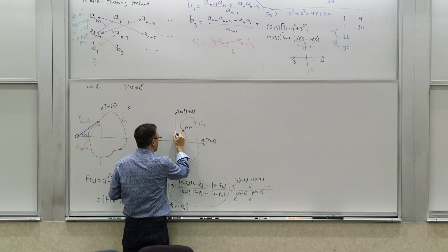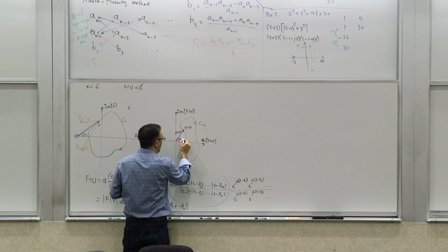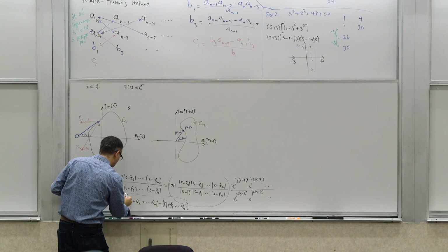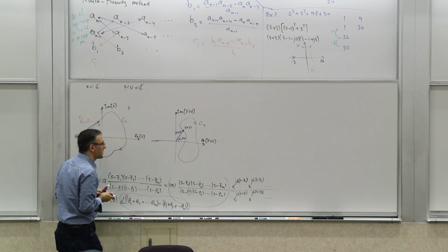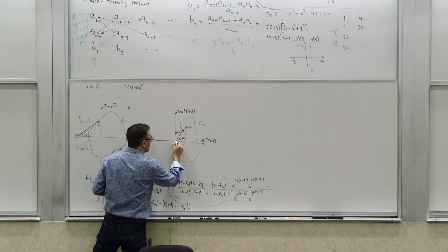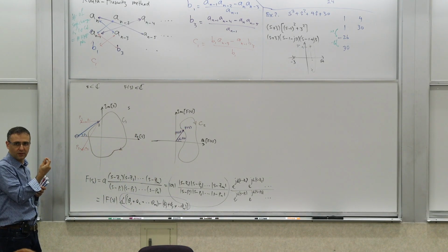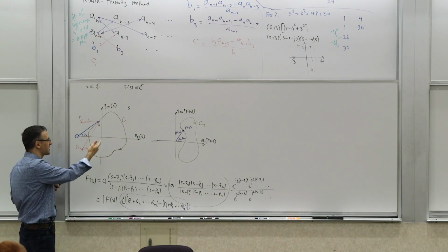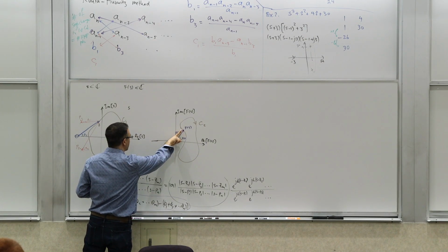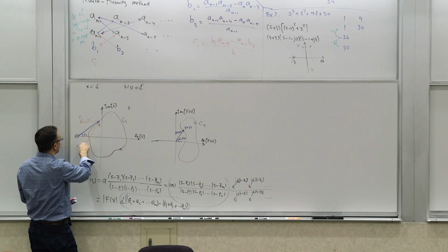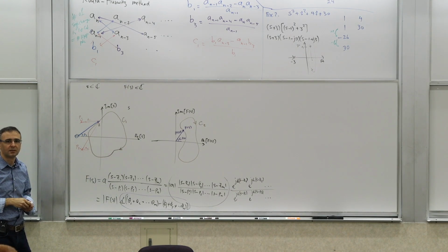And this is the magnitude, the vector has a magnitude of f. And this angle is the phase of f of s, which is this quantity. So for that value of the function, when you put an s in, the value that the function assumes will have this magnitude and phase. And this is its phase, right? Which basically says all of these blue phases minus all the red phases. Do you agree?